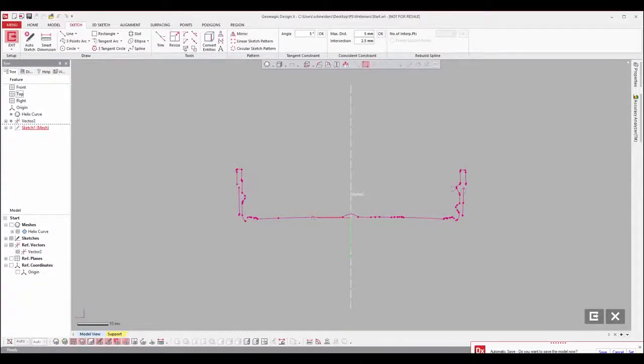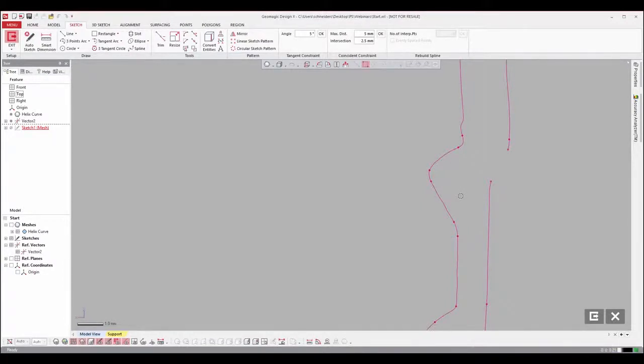We're going to focus on this top right hand tooth right here, because what we're going to do is take this profile and use it in our helix sketch to revolve it around to create our thread. Taking the line tools here, we're going to fit the top and the bottom of this thread just by highlighting the scan information here and extracting those lines.